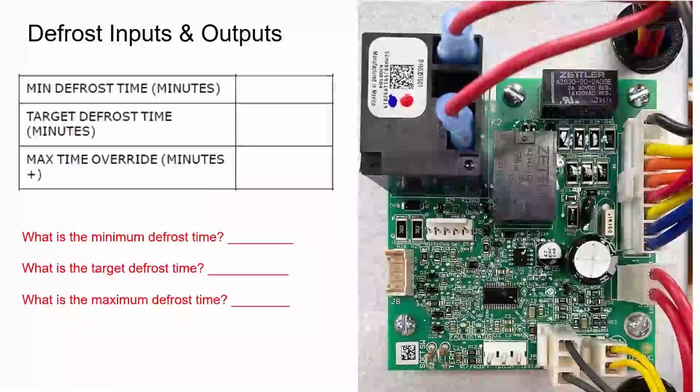So those two conditions must be met before defrost is allowed. All right, so once defrost is allowed, we have a couple of timing things that we're shooting for. And again, this is in these demand defrost quick specs. One of the things, minimum time for defrost. When we go into defrost, we will run a minimum time for defrost, and that's usually around 1 minute.